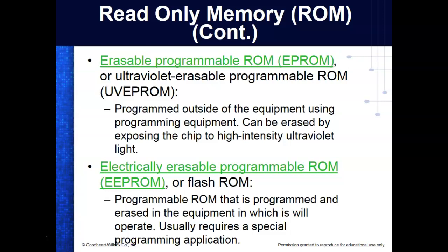So these are ROMs. But these are EPROMs. Still very, very popular. What we can do with these is erase them by exposing them to high intensity ultraviolet light. That's why you see that glass window in them. We'd have a special thing we call an EPROM eraser, which is nothing but a fluorescent light without all the filtering on it. You'd slide it in there and it erases in 30 minutes.